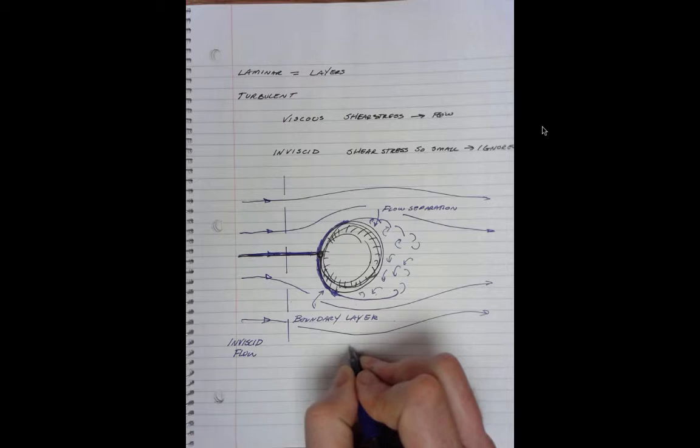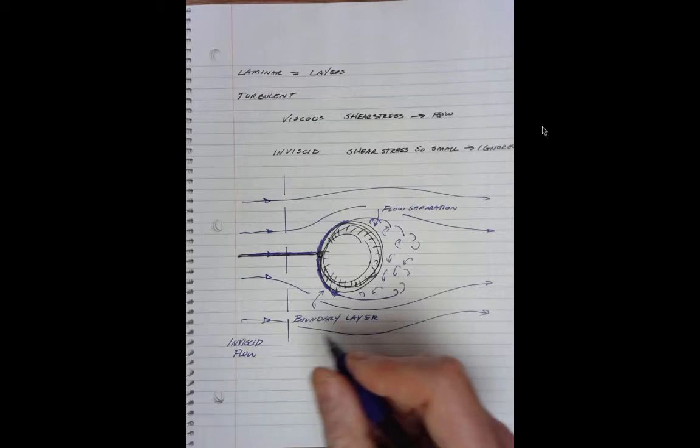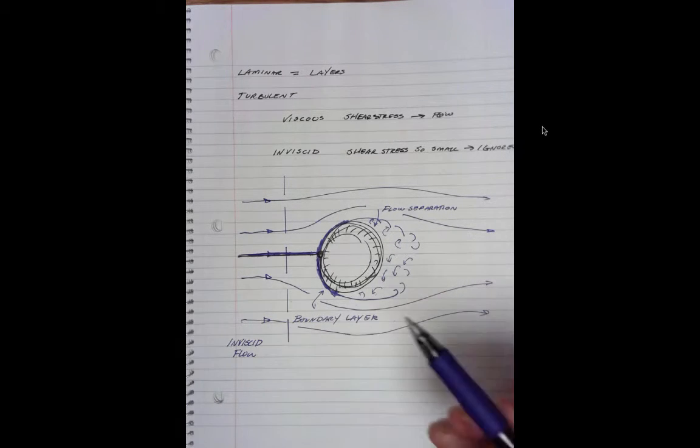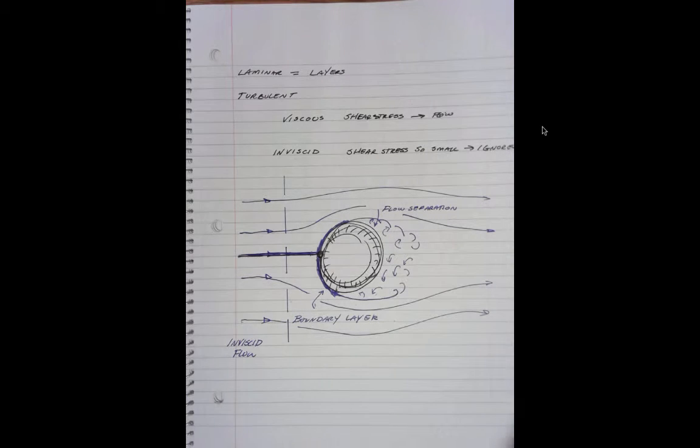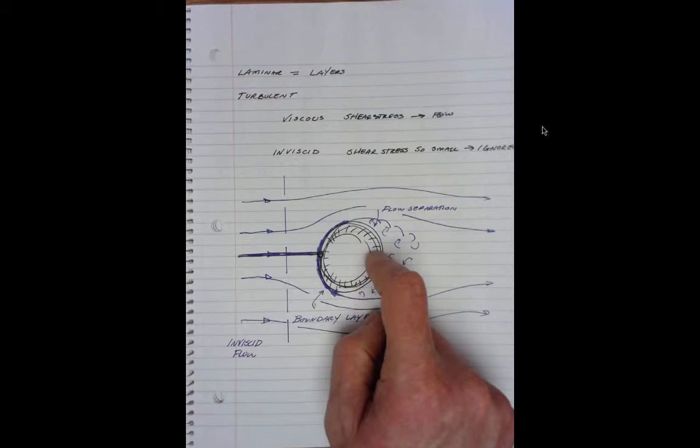And then this is not the case, and we would have to look at boundary layer, wake, and potential flow regions to describe this. So this drawing has many different flow regimes. There's the approach I've assumed is nearly inviscid. There's a boundary layer with a viscous flow along the wall. There's separation where the flow leaves the wall. And there's a wake, separated flow behind the body. So the drag force goes up when there's separation.